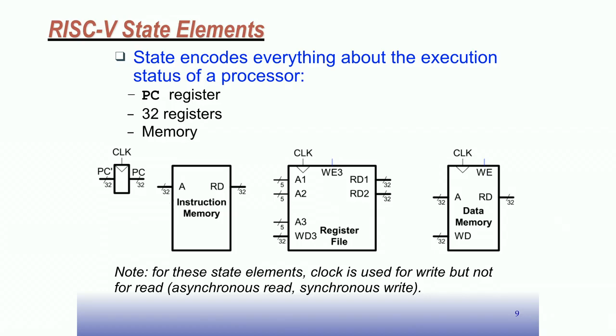And then you'll have the data memory, which is a memory that has both read and write. You can read data out according to this word address. So you put a word address in, and data will appear on the output, the data that corresponds to that location in the memory. That address will yield a corresponding data word. And this write address is used if we want to change the internal contents of the memory. You can write a word in by putting an address here, putting the write data here, waiting for the clock with the write enable, which is like a clock enable. That allows us to change some internal state of the memory.